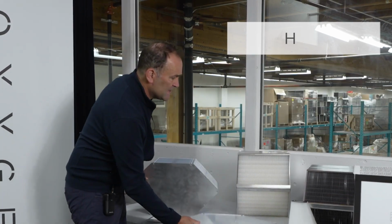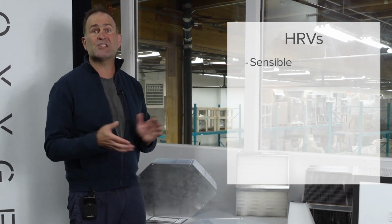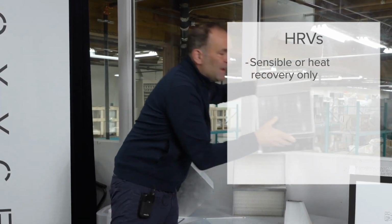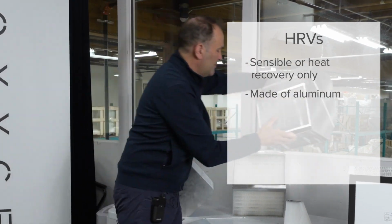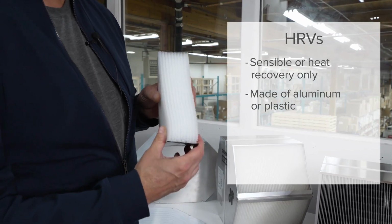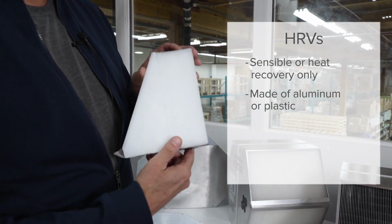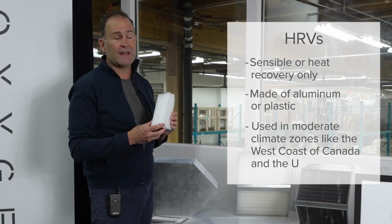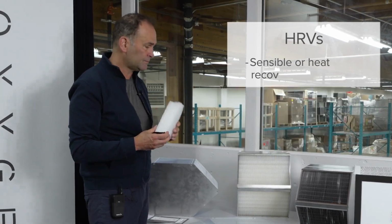The second type is an HRV core, which does sensible only or heat recovery only. And here you can see it's typically made of an aluminum material, or in this case here is made of a plastic material. And it again does only heat recovery and is typically used in moderate climate zones like the west coast of Canada and the United States.